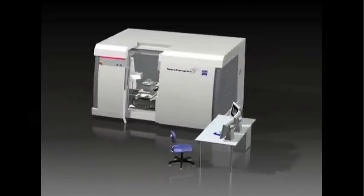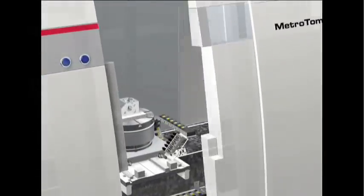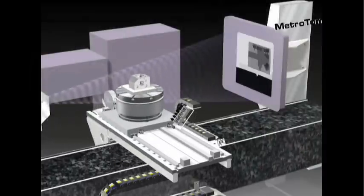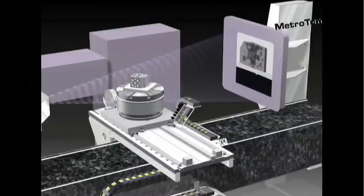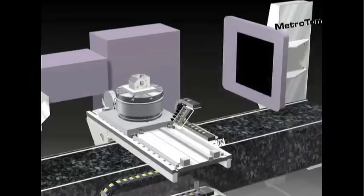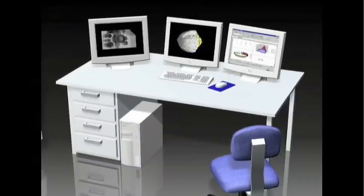Now we place the part on a piece of, again, styrofoam. The door closes, the X-rays move into the field of view, the part moves into the field of view of the X-rays, and it does one 360-degree rotation. At every single step, you're collecting a bunch of 2D projections. So it's like a bunch of 2D X-rays. Exactly. Okay. All those 2D X-ray projections are then reconstructed into a 3D data set. Now you have a data set that has both internal and external geometry associated with it.